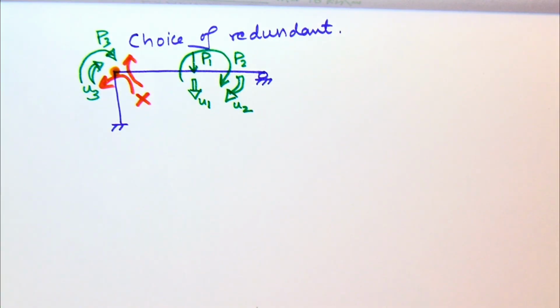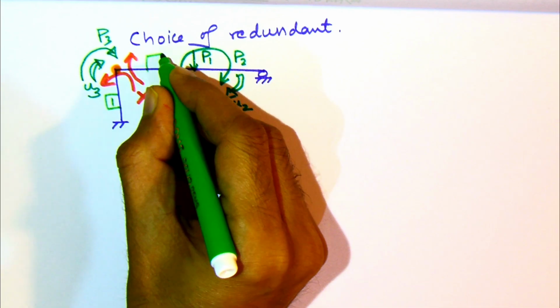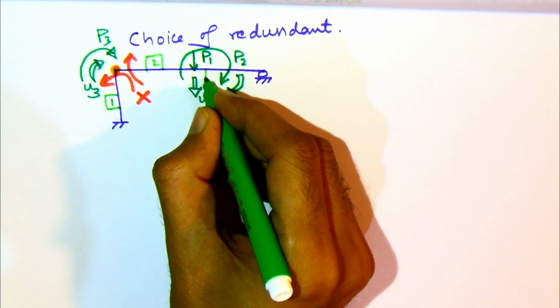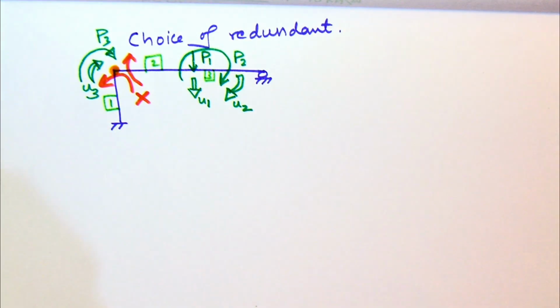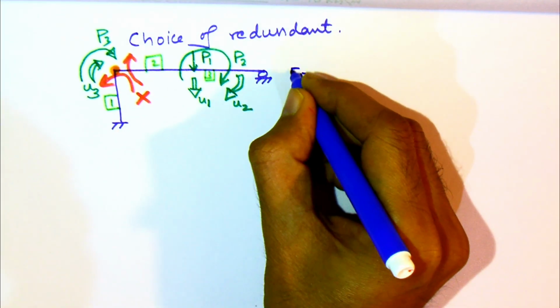So now we can form FC. So FC is straightforward now. All the members have same flexibility matrix. The size of FC will be 6 by 6 because there are 3 members. So you can form FC yourself.